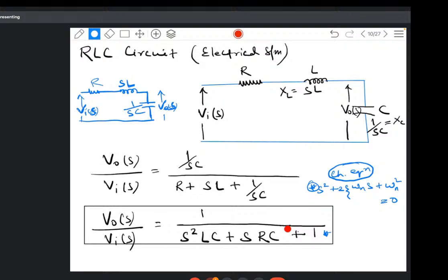Why am I using the damping ratio zeta? Okay, to damp out the oscillation, because I know that the second order system will have a natural tendency to oscillate about the steady state. So that is why I need to provide some amount of damping to damp out or to remove the vibration or the oscillation in the system. Okay. Then we have seen what is the type of the second order system. I know that second order will have order of 2, but what is the type? Type will be 1. I have also seen how to convert the second order closed loop transfer function into the open loop transfer function. So you also know the open loop transfer function for the second order system.